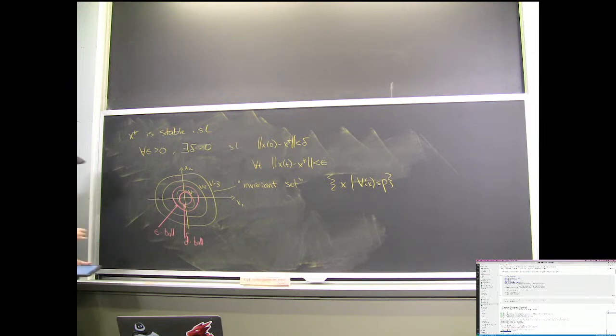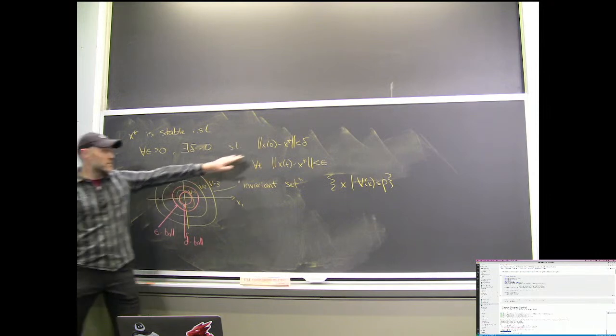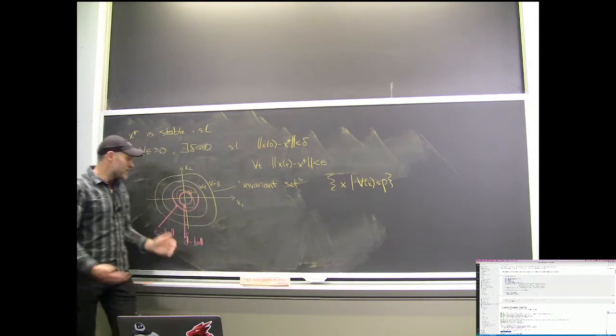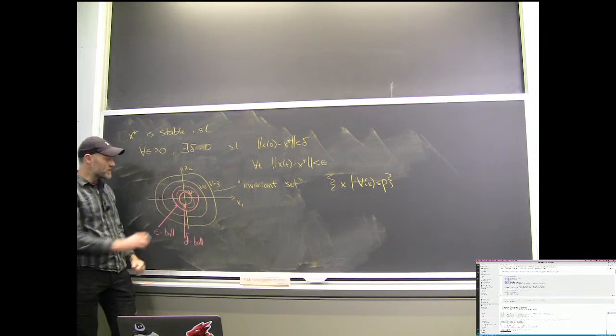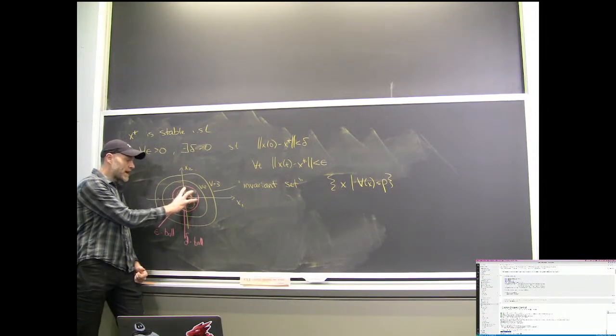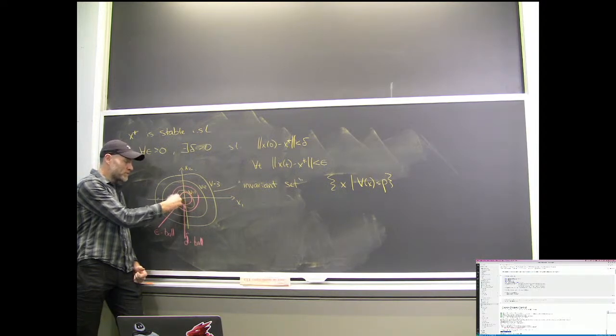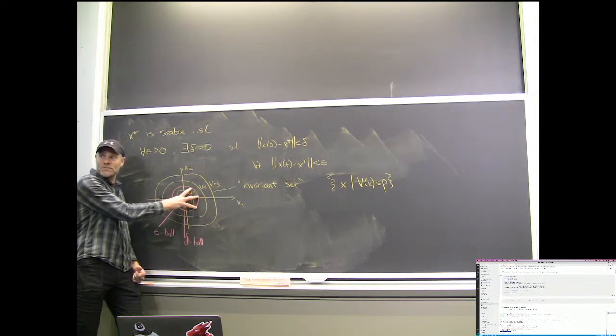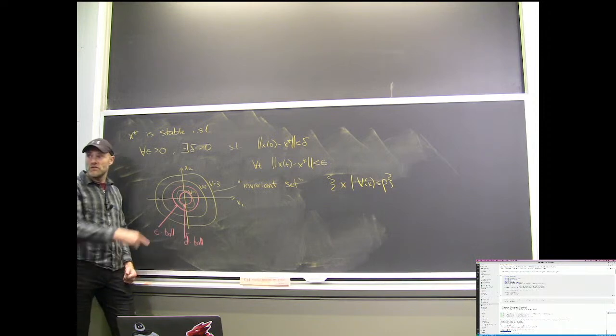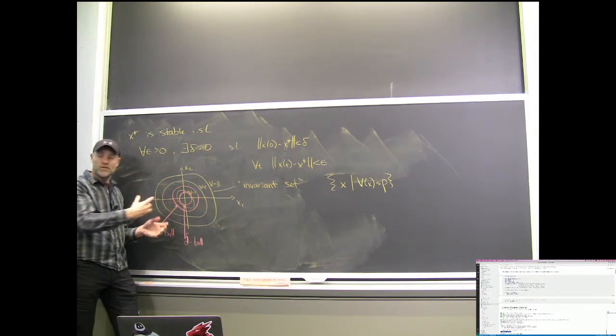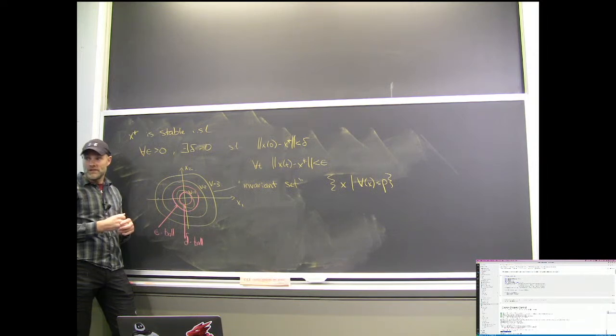So in some sense, Lyapunov stability depends on our choice of norm, right? Whether you're Lyapunov stable or not should not depend on that. And that's actually the reason we're playing this game: you can pick a norm here, and if the Lyapunov function exists, you could think of this game of inner and outer as follows. If you have circles in some norm, I can convert that into my Lyapunov coordinates and then back into your norm, right? So the two balls exist just to be robust to the norm, in a sense.